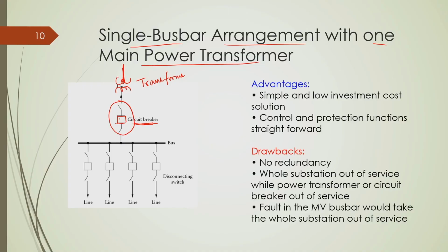Okay. Now, with a circuit breaker you have two additional switches. These switches are called isolators, and these isolators are also switches. Circuit breakers are also switches. Then what is the difference? Circuit breakers can be operated at load conditions, so on-load operation is possible, but isolators are always operated at no-load condition. So, they are no-load operative switches, and circuit breakers are on-load operative switches.